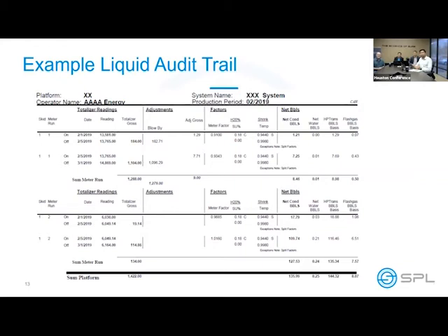In the adjustment section, we have a blow-by noted. This would represent when we have gas that's carried under into the liquid meter and thus overspinning, in this case, a turbine meter, and the adjustment for that. We may have some adjustments in the adjustment gross that could be due to a variety of things. Maybe the meter froze, or maybe the meter stopped counting for any number of reasons at any given time. All of those things need to be brought into account when we talk about adjusting the gross meter readings, ultimately to calculate a net.